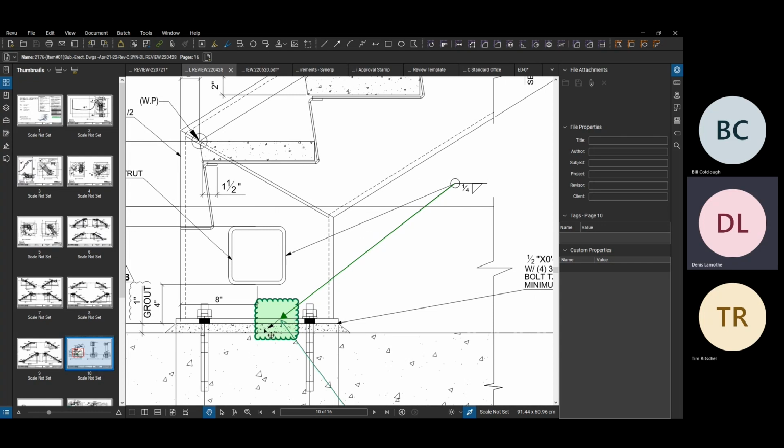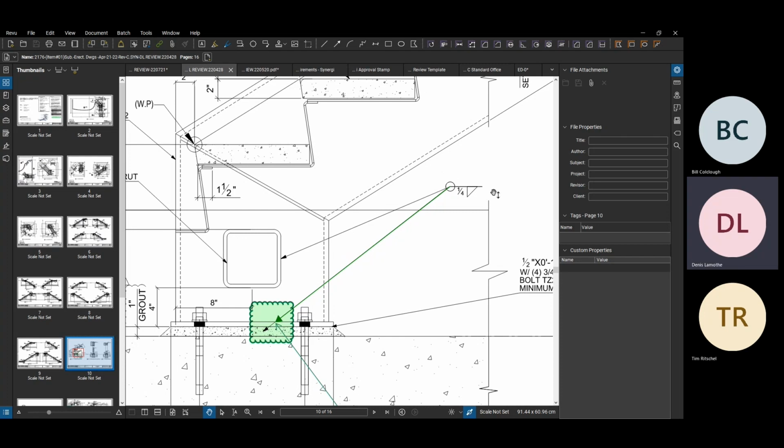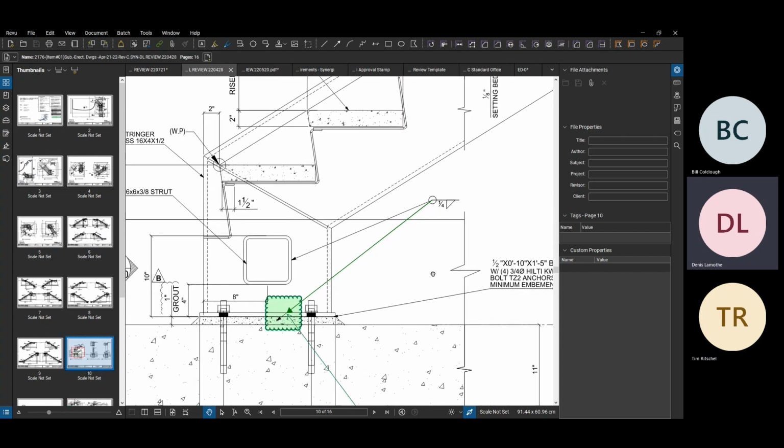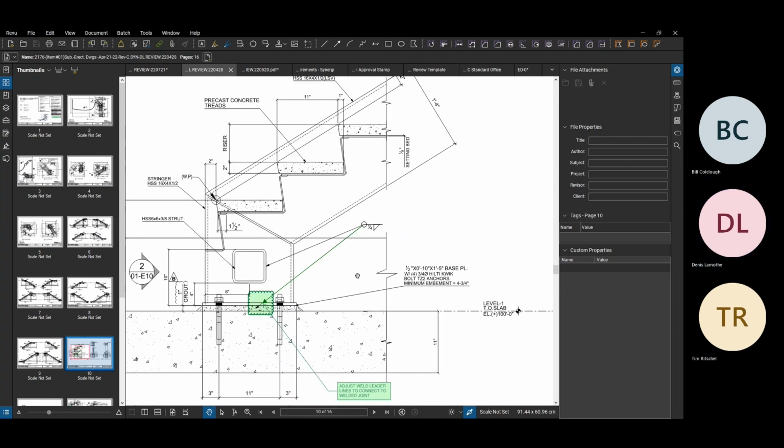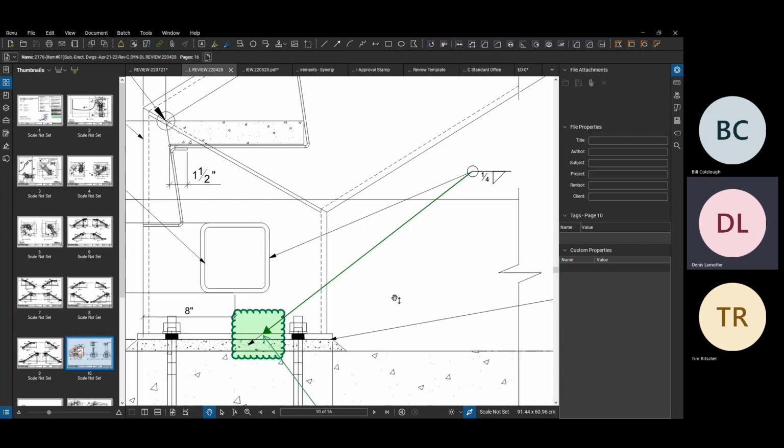Usually we'll have engineered sketches by this time that you're checking drawings. So check with the engineer sketches that they provide, and if they've included a weld type that they want you to use, and a size, and maybe a spacing. If it's a longer seam, they may specify a 2-inch long weld every 12 inches or something. So just make sure that information is all there and it matches the engineer's sketches. If it doesn't, and there's an issue later on, we are liable for it because we are not following what the engineer required us to do. So it's kind of critical that the welds match.